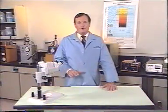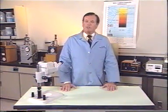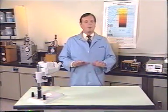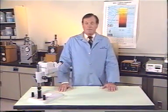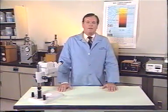When cast materials are used, the desirable design features are uniform sections, mild strain gradients, and short flake graphite microstructure. In oil-fired and gas-fired furnace heat exchangers, the thermal cycle is very important. The thermal cycle controls temperature gradients. In thin sections, external constraints are of minor importance.